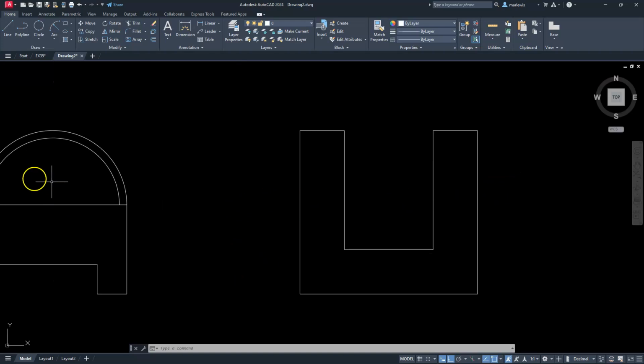One other last thing we need to do is put the line that's going right across here, right? So let's go to line. I will touch this intersection or endpoint. Once it tracks here, I will left click at that intersection, then go right across to here. Let's escape out of that, and then go to trim, and trim off the portion in between.